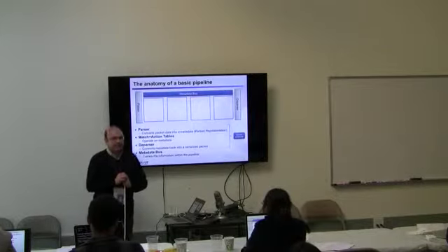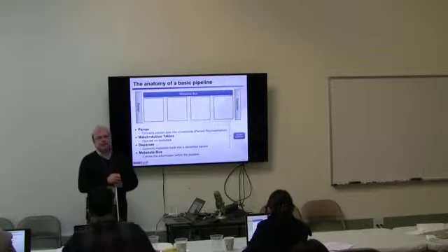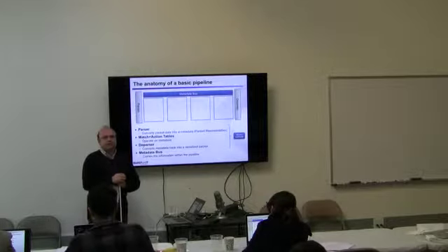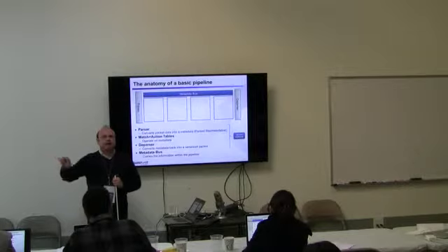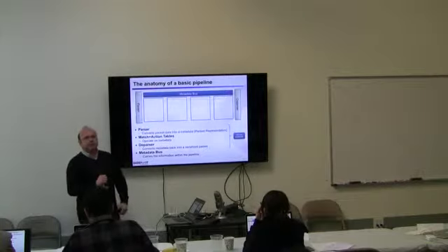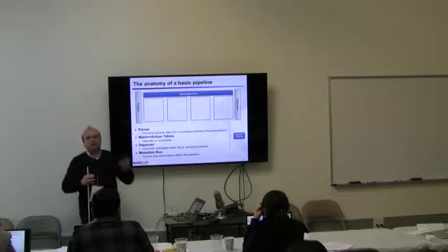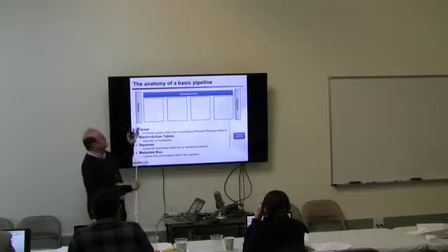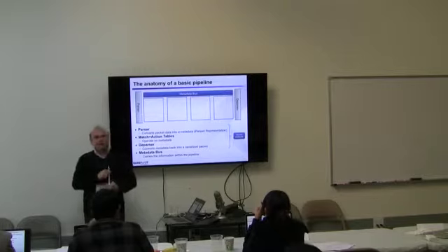So technically, if we talk about how things are done on the real chips, normally yes. Normally they have cell organization, and typically whatever is not really required for processing is being sent away directly to the buffering mechanism while this portion is being processed. And that's really important, right? Because here we're talking about maybe 100, 200 bytes. The packet can be very long, and this processing starts whereas the MAC is still busy trying to get this data.